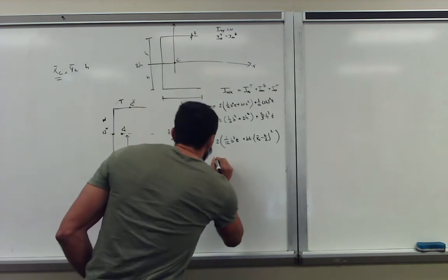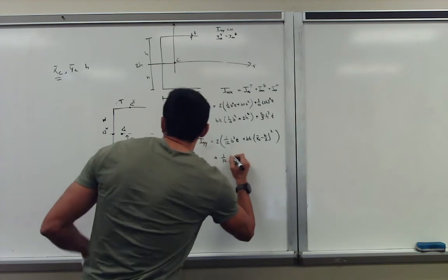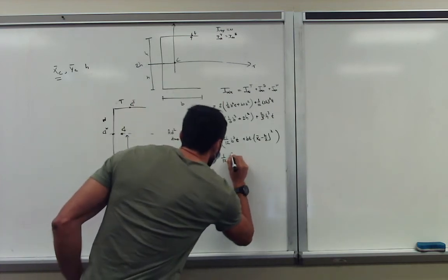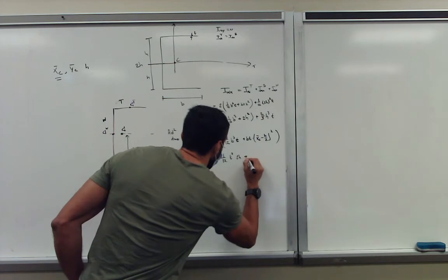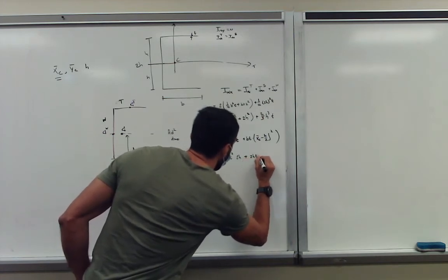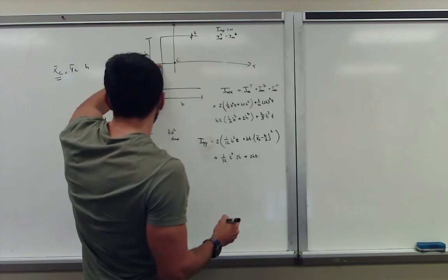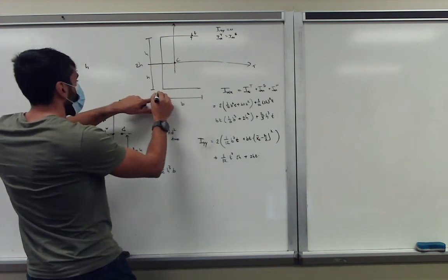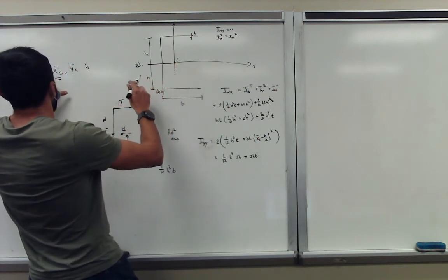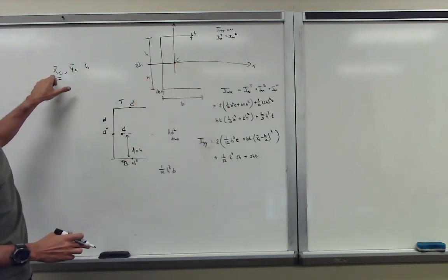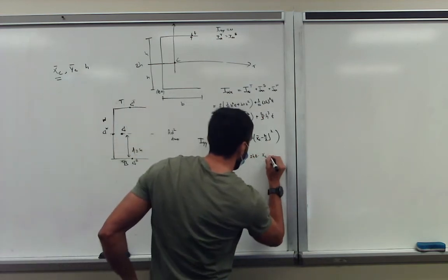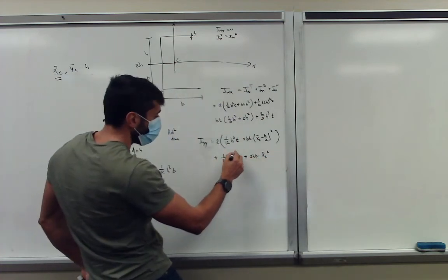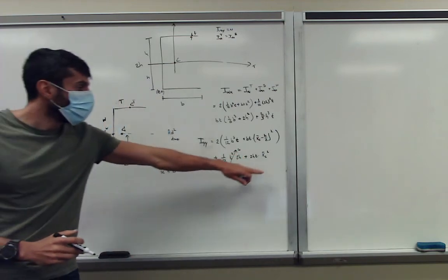And then if you do the moment of inertia of the web, you get 1/12, and this is again b cubed h. So you get t cubed multiplied by 2h plus the standard term, so that's 2h t plus, in this case, the distance you shift. If you calculate xc with respect to 0, 0, then this is basically xc squared. So you multiply by xc squared. And then you can say, well, this is t to the power of 2 and higher, so this one drops out, so this becomes 0. So this is now your moment of inertia term.